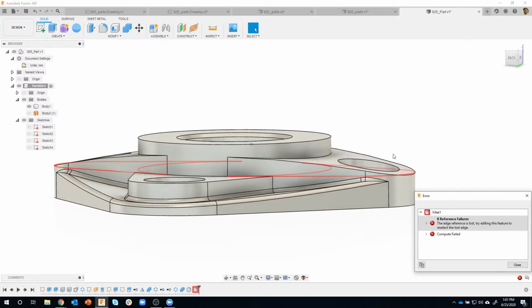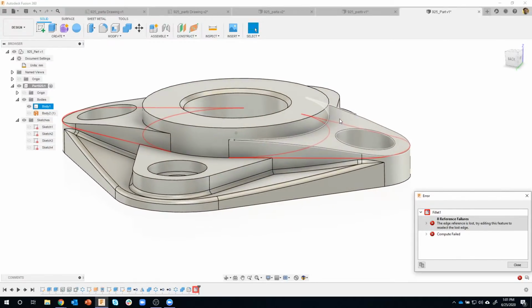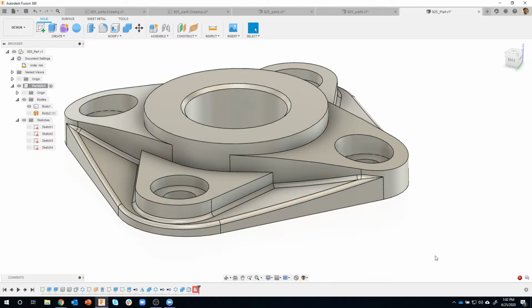And hopefully you guys are figuring out what's going on here. This fillet was created on edges before they were changed in time to a curved surface. Okay, so unfortunately in this case, it's looking for these edges in time, but then we came along, we created that surface, we did the replace face, etc. So it basically lost, it didn't know where those edges are anymore.